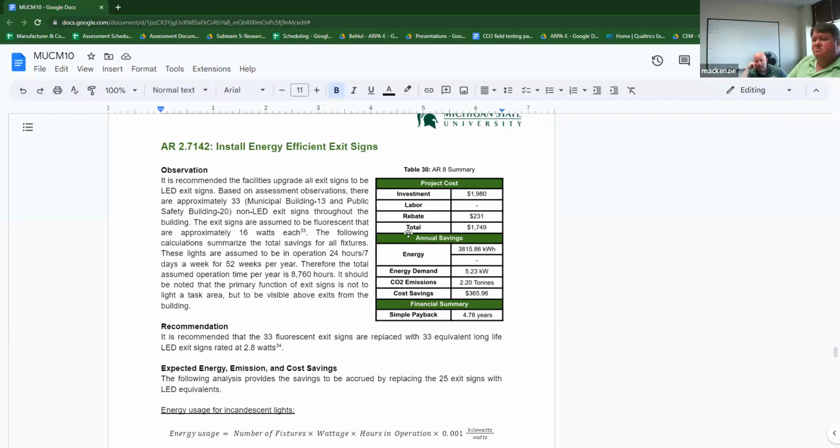We energy people have been trying to change the standard on campus to put a VAV box in every room. In some cases there are 3 rooms served by a VAV box and only one is in use, so you're ventilating 2 unoccupied rooms, which is necessary when one box serves multiple rooms.